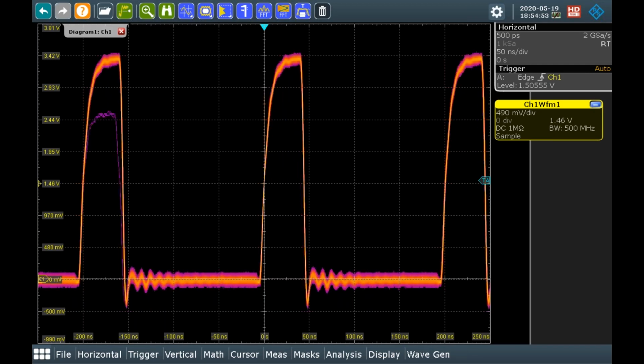Let's see, it looks like we have a question about, is this the same as letting a scope run for a long time? The short answer to that is yes, you can get around not having a high update rate by letting a scope run over lunch or over a weekend. It's a lot easier to just have it up front, right in front of you. So that's what we talk about at the first part of this section of test coverage. So you're able to have a higher statistical probability of finding these glitches in a much shorter amount of time.